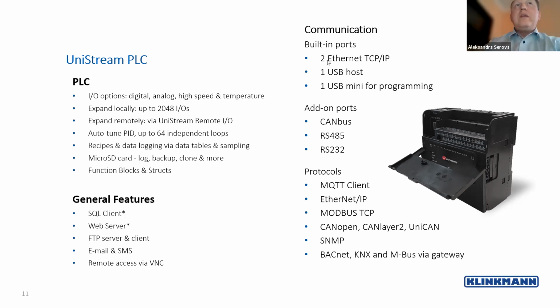What can also be interesting is that the devices have 2 Ethernet TCP/IP ports on board, so you can connect the incoming cable to the PLC, and use the second Ethernet connection port for additional modules. So you don't need an additional switch, as an example, to connect to your device and maybe a display on your cabinet.